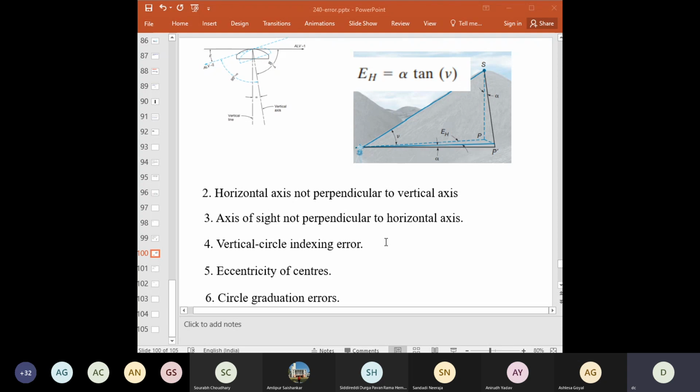And with a total station having dual axis compensation, this error can be determined in a calibration process that consists of carefully pointing the same target in both direct and reverse mode. Once that calibration is done, this error will be sensed, and this operation will be captured in the microprocessor circuit and the program, which can compute and store the correction factor.